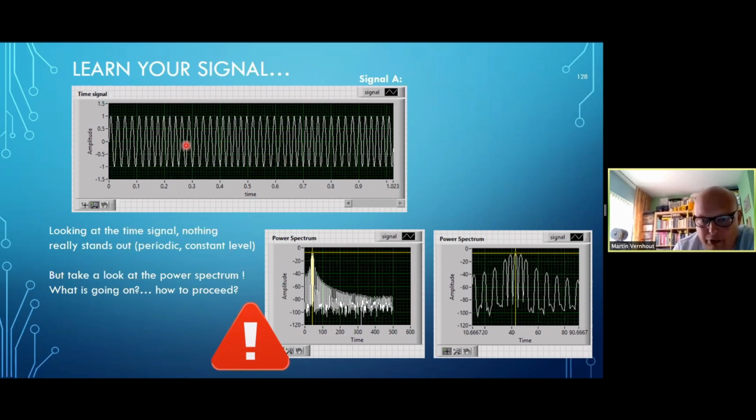Still, if I convert it to my power spectrum, to my FFT, my frequency domain, it looks like nothing I would have guessed, because I would have expected one single line at one frequency, but it's actually a whole lot. And there is nothing with a filter or a window I can do to make this change. So what's happening? Why is my sine wave not perfect anymore?